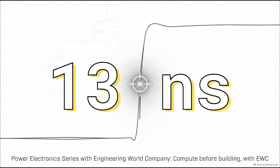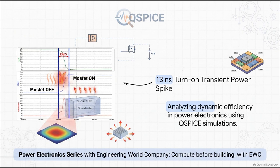13 nanoseconds. That is the extremely brief window of time we are about to zero in on. Just 13 billionths of a second. Diving straight into a single switching cycle, we expose the 13 nanosecond MOSFET turn-on transient. See that perfectly vertical line from the macro view?